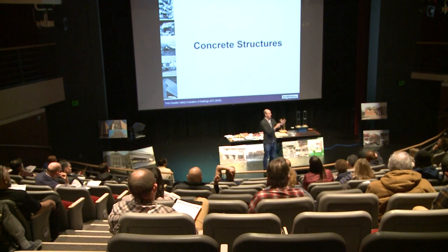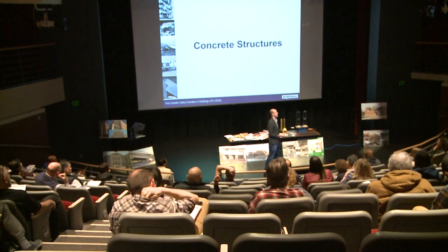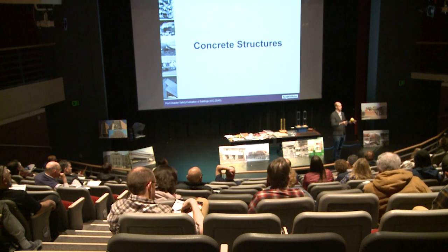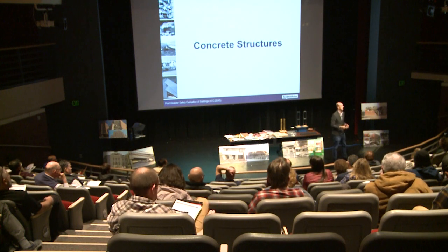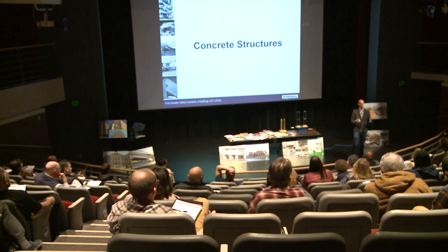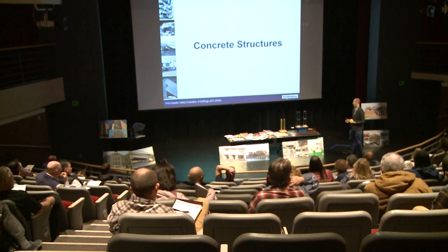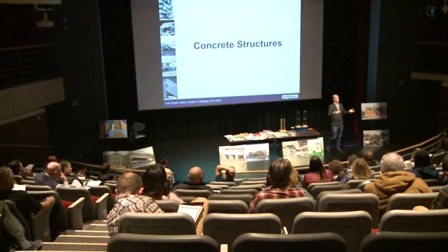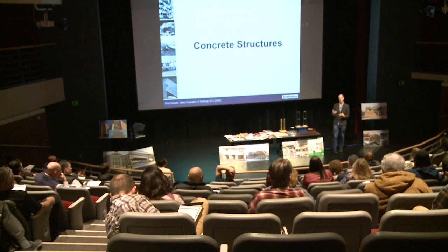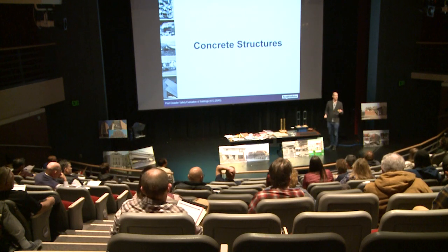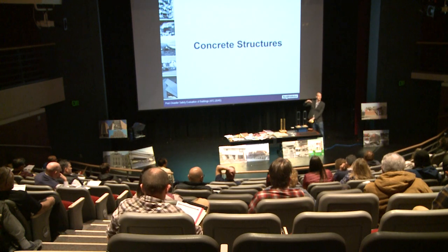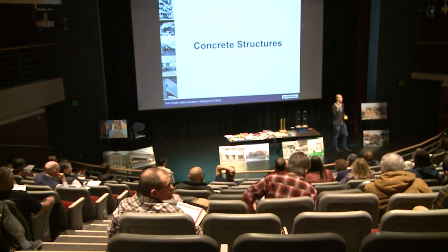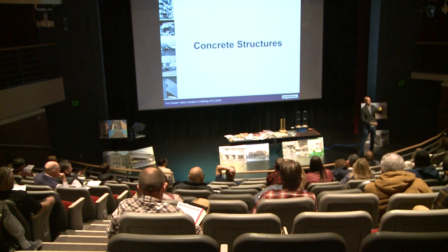One, I'll say, that's the disclaimer, all things being equal. A bunch of the examples that we've seen have weird things going on in the buildings, irregularities, to use the terms we talked about, vertical setbacks and stiffness discontinuities where there's more wall and different amounts of wall. Think of what we talked about with the dynamics of two different buildings. What if you have a building that's real wide and then sets back? You effectively have the same dynamic, pun intended, of different dynamics compounding on the stiffer part of the building and the more flexible.